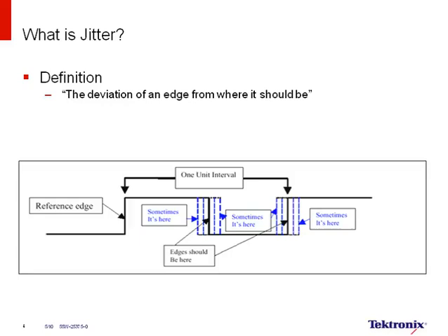And what's critical here is there is statistics associated with this variation: a peak-to-peak, an average, min-max, and standard deviation. This is fundamental for truly understanding how to make proper jitter analysis.